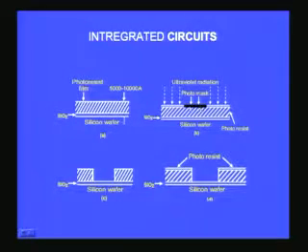Then wherever the light comes, for example, in this region there is no mask, and therefore the ultraviolet rays reach here, and they react with the photoresist film, and when you develop it like a photographic film, you would find these things will go away and they will expose the rest of the region below it.